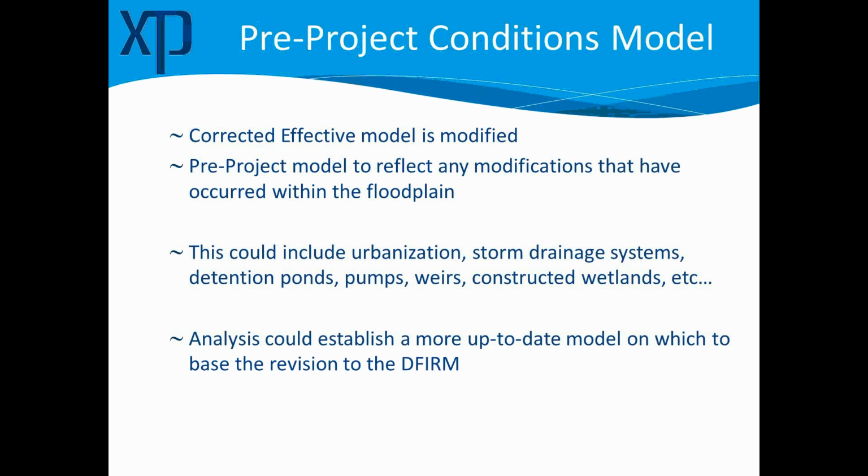In a full dynamic model, you don't do that because the routing is handling the full equation of the shallow water equations, and so attenuation of flow as you go downstream, or routing, is accounted for in each time step between nodes. So that could very well equate to a hydrology change. Not a hydrology methodology change, but a hydrology result change. There's sections on the forums, of course, for that. So that's a good question. I'm glad that was brought up, and that very well could be an effect.